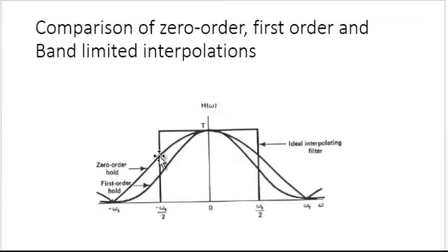If you notice over here, this is a little bit curved with respect to this ideal filter. First order is still more curvy than zero order hold, so you will obtain a more approximate signal with respect to the input signal. If I go for a second order filter, I can have still more curvy of the input signal. Like that you can have different types of interpolation processes.